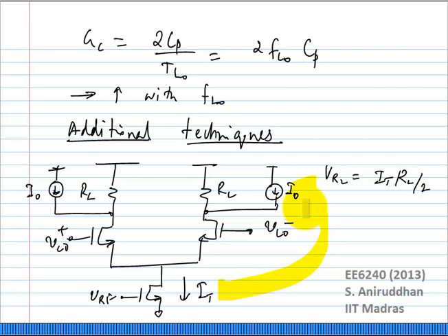Ideally these devices should be high impedance and they should be ideal current sources. However, remember that you are going to be experiencing some swing at these nodes, okay. And when these nodes swing, you will need to maintain these extra current sources I0, the PMOS devices, in saturation region. So linearity could be an issue.